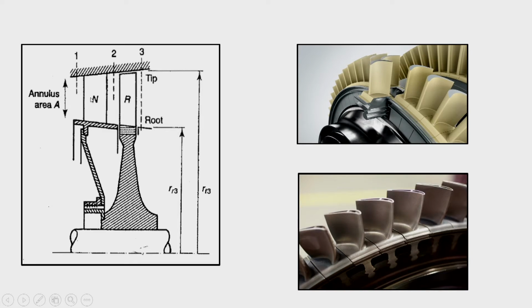When the flow enters the nozzle, as the name suggests, the nozzle's job is to increase the kinetic energy of the flow. Here we expect the flow to have a decrement in pressure and an increment in velocity. So this high velocity flow would flow over the rotor.